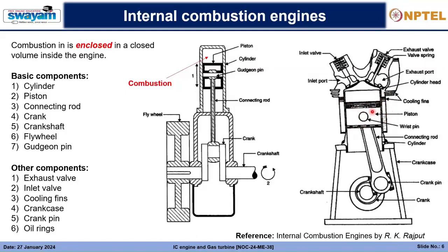So that is the cooling part, and the other thing is the oil ring. You will see that due to the reciprocating action of the piston, it slides over the cylinder walls, and accordingly due to friction it can wear out, right? So just to avoid the wear out and also provide a seal for the combustion materials to not flow out and just combust in this enclosed volume, we have oil rings in here. So these black marks you will see, these are basically the oil rings.